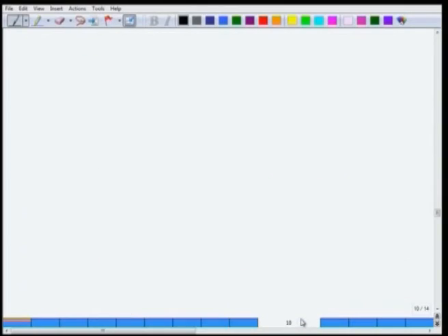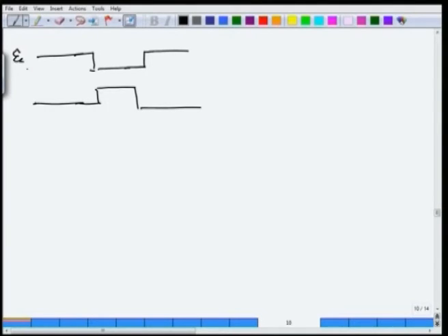Also in LEDs, you will have to take a semiconductor which is like this, another semiconductor in the middle, and then another semiconductor which has a bigger band gap. Three semiconductors like this, and you are going to make LEDs with this. This will be Ec and this is Ev before joining. When you join, this nature will change, as you have seen.